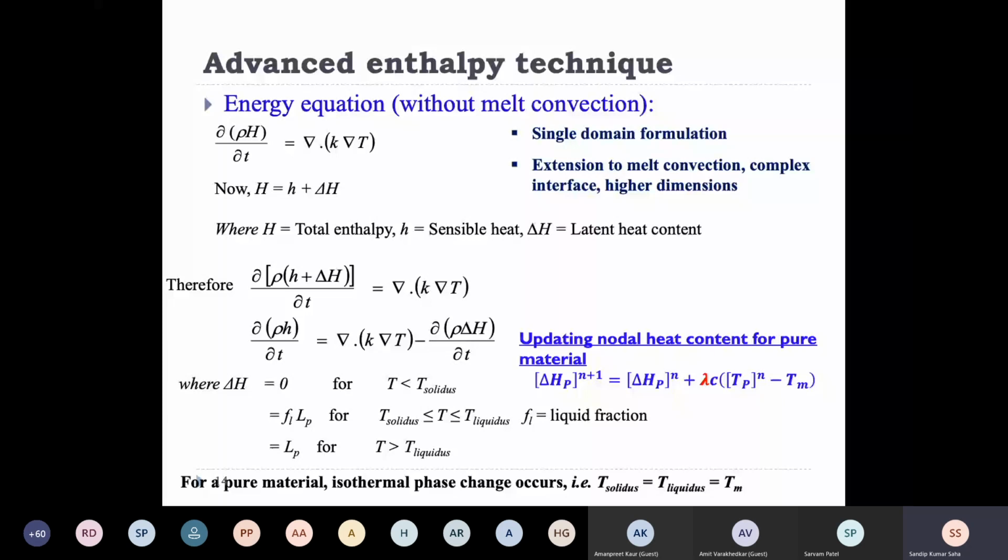The value of the relaxation factor is given as 0.6. We don't change this, but if you change it, you will see that the solution will not change much. Normally we take 0.6 for this case.